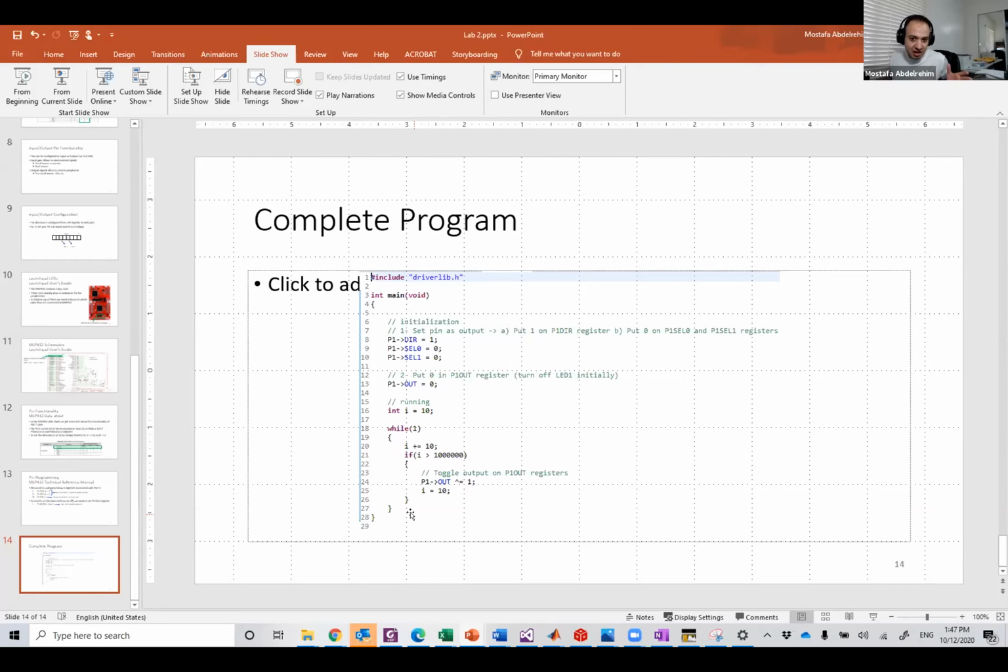What we want is a delay, so the LED will be on for some time, then off for some time, and so on. This is one way to do the delay, but it's a very bad way. In the future, we're gonna learn timers, and we're gonna set this to exact time, for example, 1 second on, 1 second off.